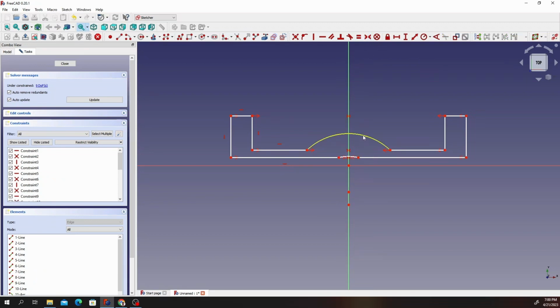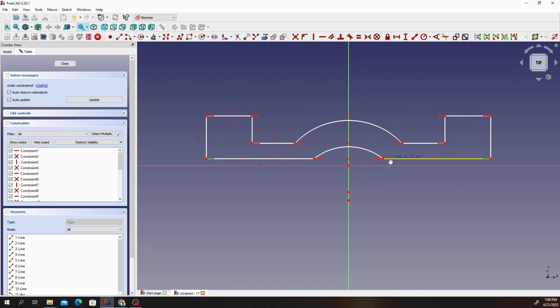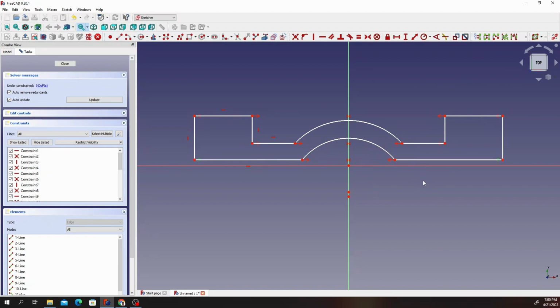Okay. So once you have the symmetry locking up all these points, we're going to go to dimensions. You may ask, why are we doing symmetrical constraint? Since this part is going to look the same on both sides, it's just better to get the plane it's rotating at, and then define the dimensions on one side, and this will be automatically applied on this other side. Let's have a simple example and you see.